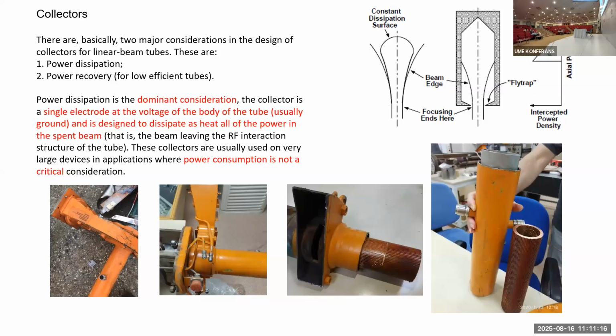When it crosses and passes this field, then it's trapped inside, because it cannot escape and loses some of its energy after striking the wall of the collector. Then it doesn't come back to the Klystron. If it comes back to the Klystron, the resonance will be down, and you can lose the beam and other effects. And then you have to trap it very well.